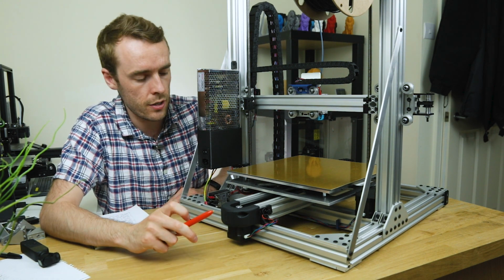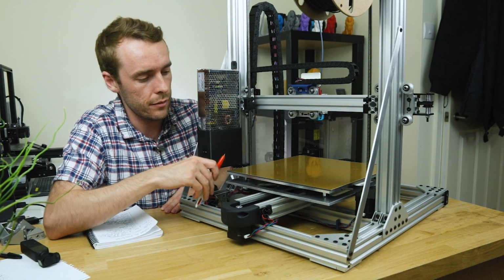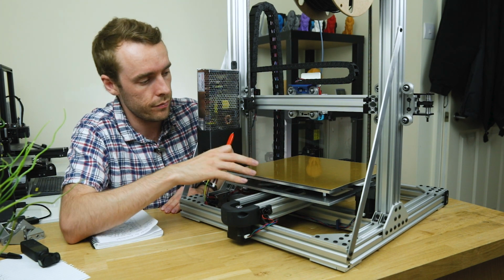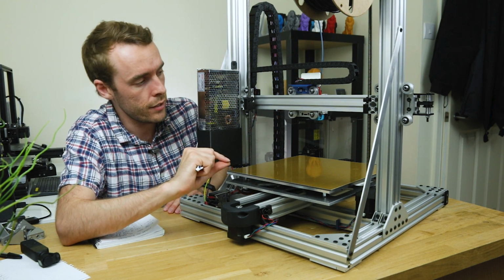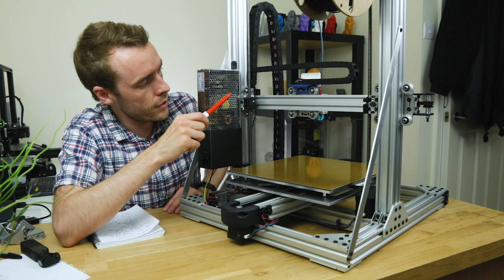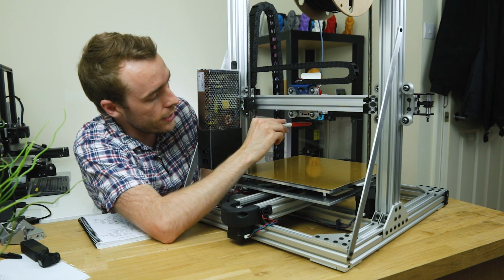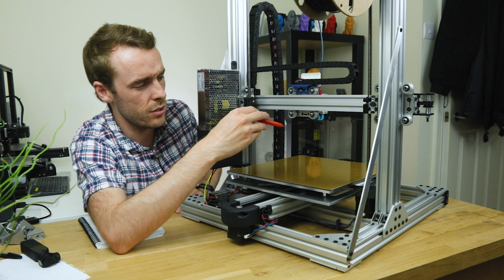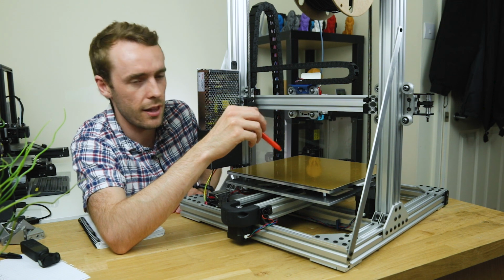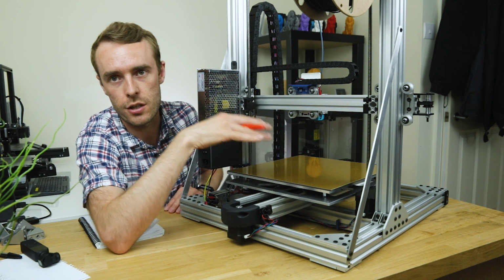Another issue along those lines is the levelness of the bed. Now, at the moment, it's mounted fairly rigidly. There's no springs, so that is one very good thing. And we're using the Pinda probe, that's the Prusa term. We're using an inductive probe to measure many, many points on the bed. I think we're doing like a 10 by 10 grid or something like that, so a huge number of points, and it makes a really nice mesh, and it does all the adjustment.